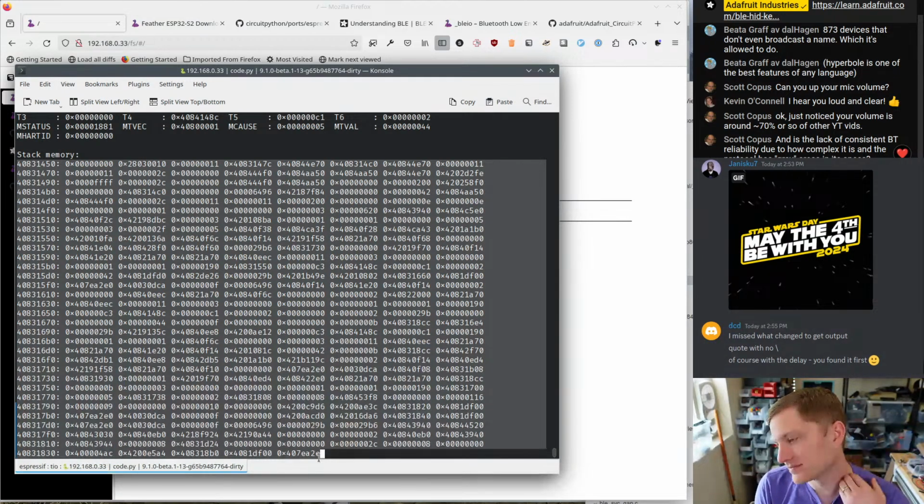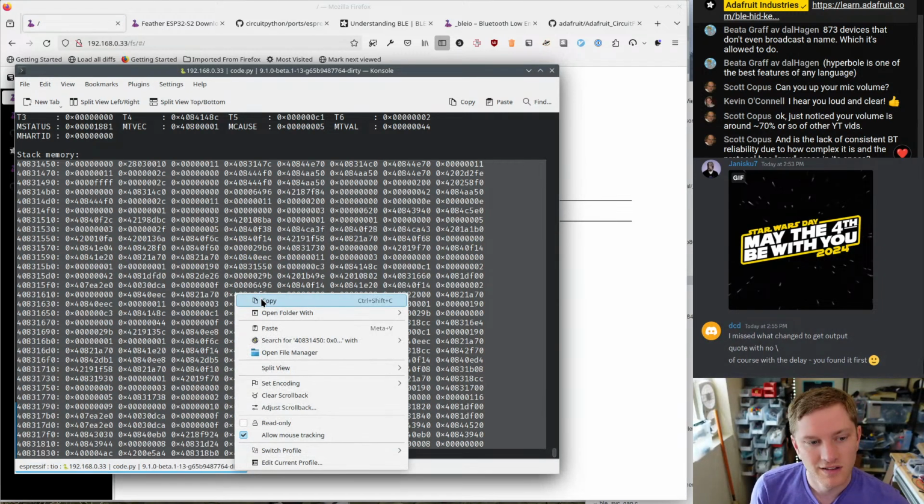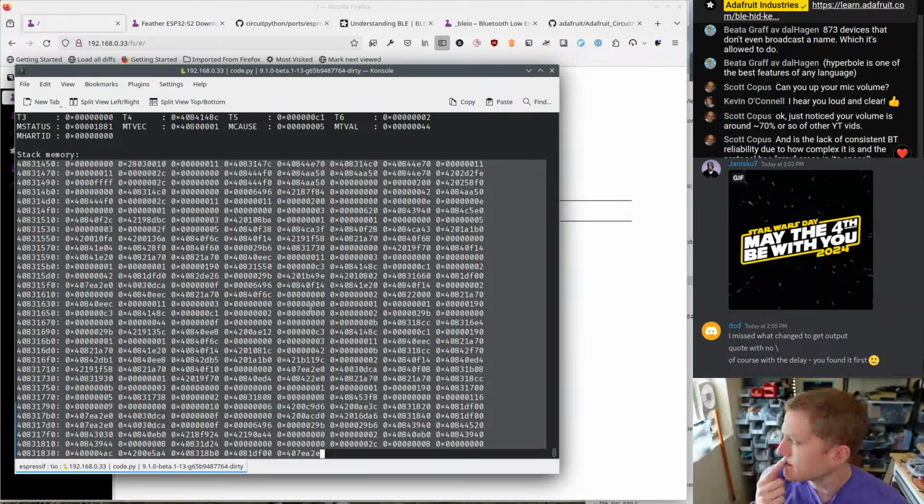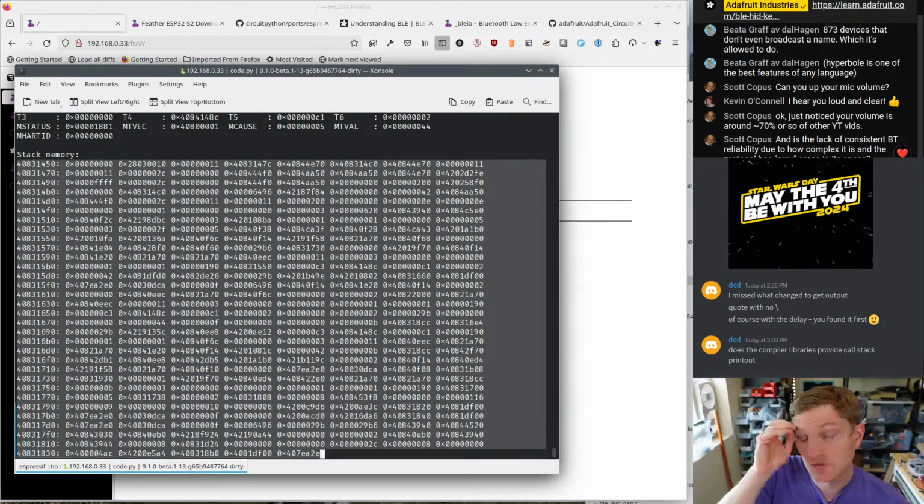It's kind of a huge pain. Usually it'll say backtrace colon with the extensive stuff, but this is a RISC-V core. The C6 is a RISC-V core. So I think I actually want to extend, I'm going to do more stuff on this, so I think it's worth doing this exercise. So this is the complete stack. Some of these values are going to have to do with functions that have either been called immediately in our stack trace, or kind of were in our history of stack traces. So I think what I want to do is make the script I have for looking up the backtrace stuff off Extensa just kind of work okay with a dump like this.